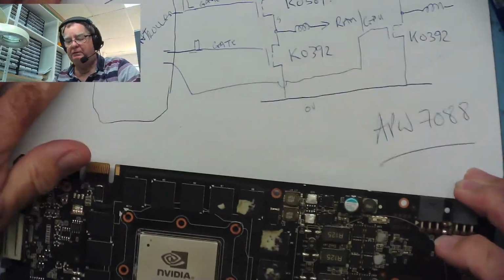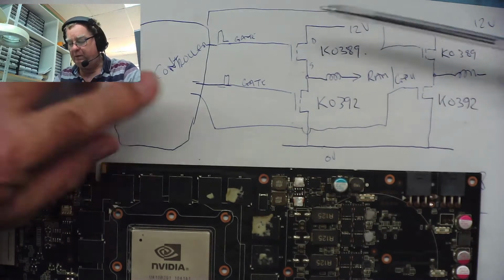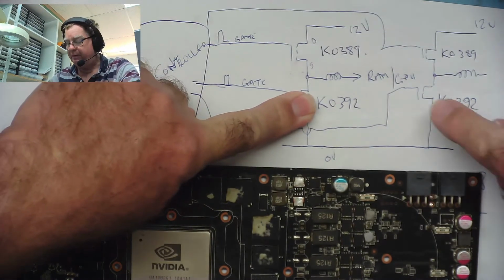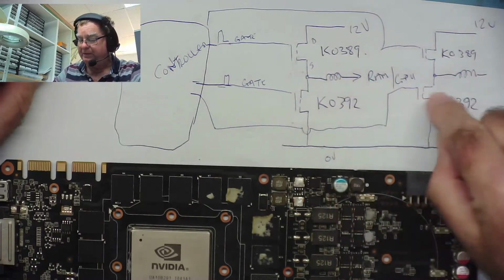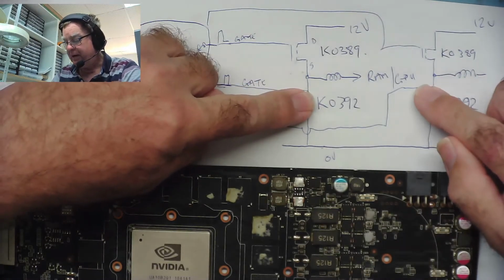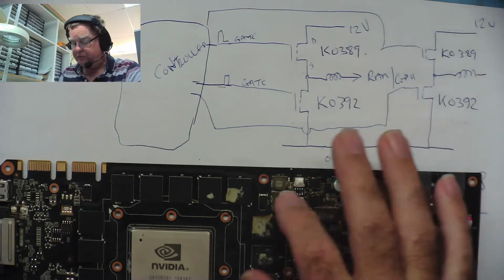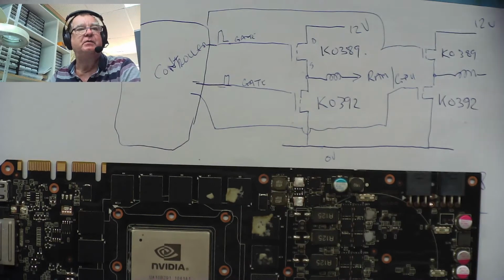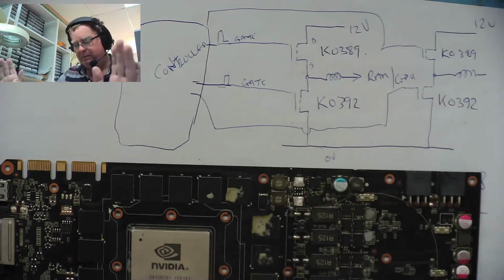Let's get into view. I drew the circuit here, and I'm looking at this circuit, and I'm saying, okay, look, if we remove this FET and we remove this FET, we've effectively removed from this coil the path to ground. So there's no ground on the end of the coil anymore, yeah? And then we should be able to see where the low resistance is, and it didn't help. If anything, it's just slightly low on this side, and this side the same as before. And I thought, yeah, that's good. So the fault's on this side, and I was already convinced that's the problem, so that's it.